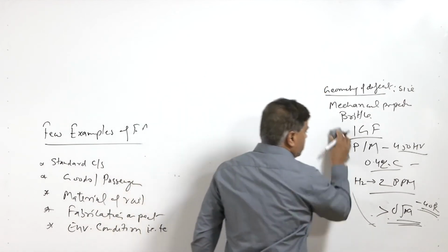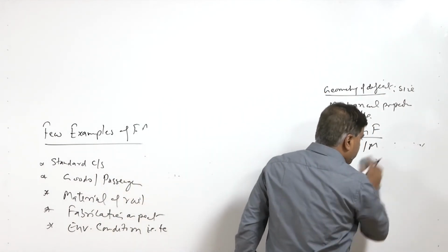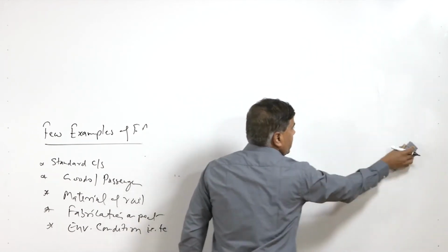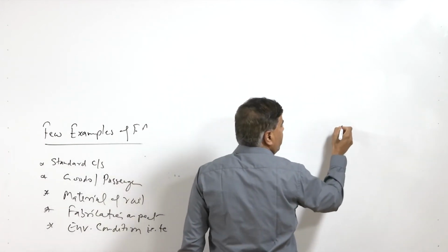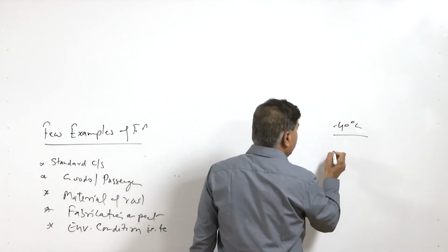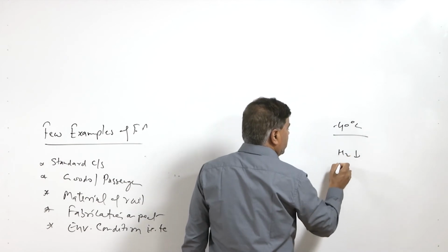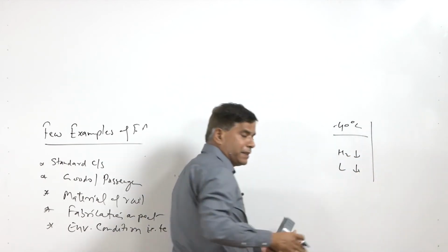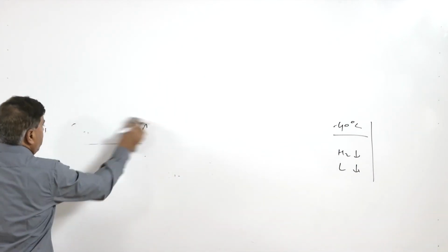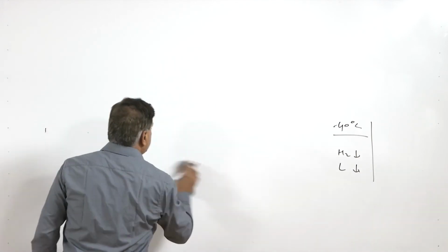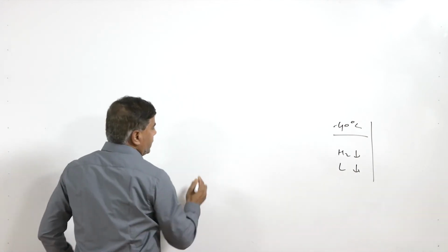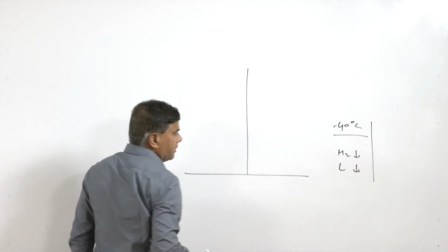And for that, the direction of our study will be altogether different. If the conditions are established such that the temperature at the time of failure was say minus 40 degrees centigrade, and the hydrogen concentration was very low, and the loading was also very low, lower than the normally allowed stresses at the time of the failure, in that case we have to conduct one additional study, the study under simulated temperature conditions, and for that we need to study the ductile to brittle transition behavior of the rail steel.